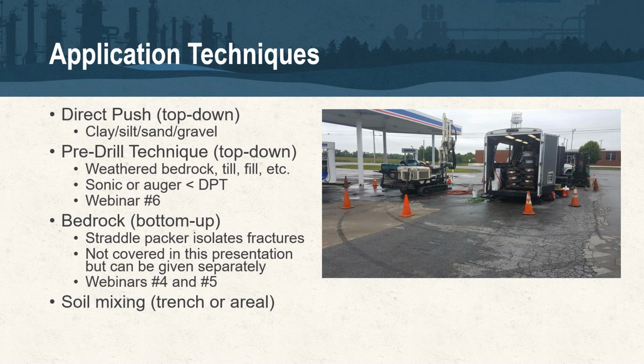So that pre-drill that I had talked about before, and that's the focal point of webinar 6, we're using that to get through, in situations where we've got weathered bedrock or glacial till. So in the Pacific Northwest or Canada or in the Northeast US, where we've got a lot of glacial till geologies, we can use this technique, again, weathered bedrock, or if it's fill material. We have a site in New York City, for example, where we're dealing with fill material.